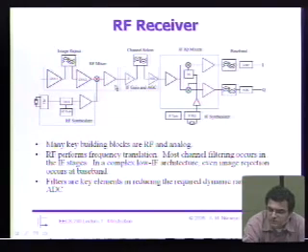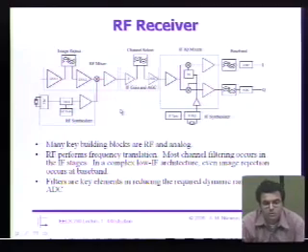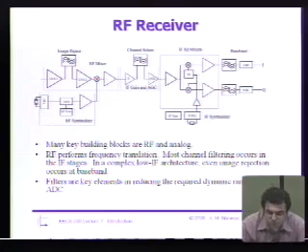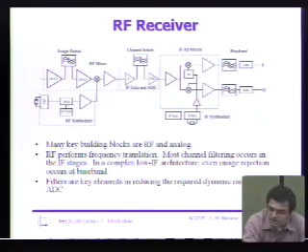But once we bring the signal frequency down to this intermediate frequency, from here forward the processing is mostly what we call traditional analog signal processing. That usually is filtering, some further amplification, probably a variable gain amplifier or an AGC circuit, automatic gain control, then some more filtering, and then basically digitization at the very end.